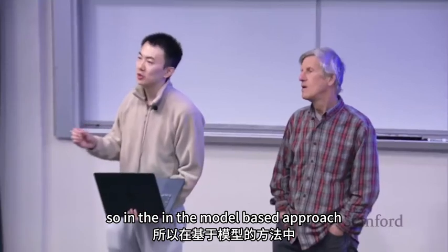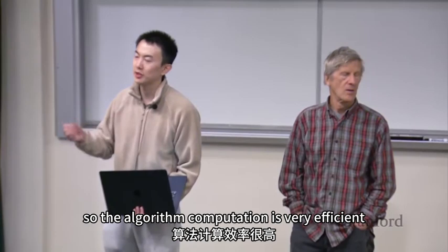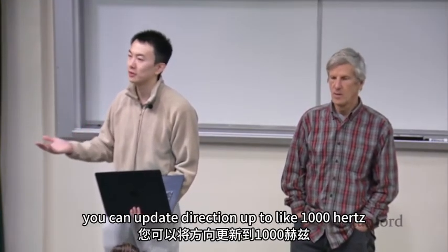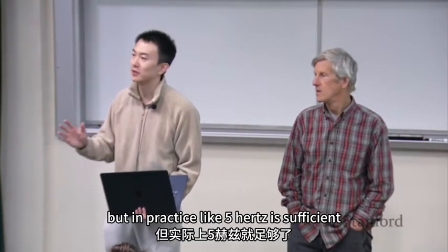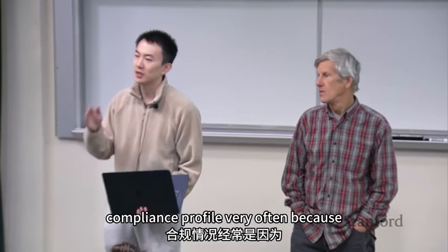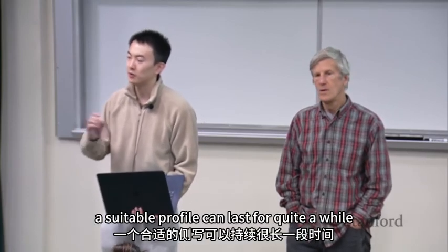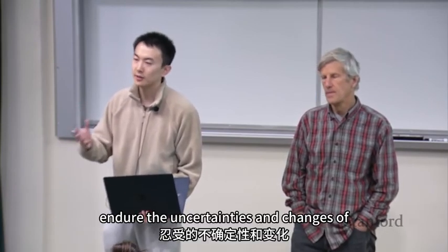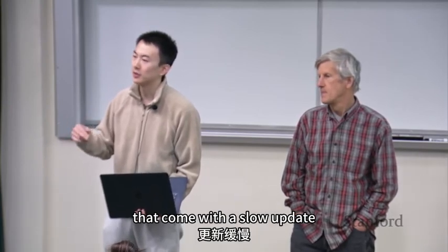So in the model-based approach, that's a decision made by yourself. The algorithm computation is very efficient. You can update the direction up to like 1,000 hertz if your computation permits. But in practice, like 5 hertz is sufficient. You don't need to change the compliance profile very often, because a suitable profile can last for quite a while. It can endure the uncertainties and changes that come with a slow update.